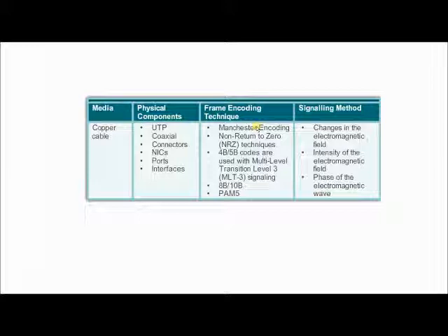Then there's the signaling. This is how the 1s and 0s are represented in the signal with pulses. There are two ways of doing this. In an asynchronous way, data signals are transmitted without an associated clock signal, the time spacing between data characters may be arbitrary, so the frames require start and stop indicators.